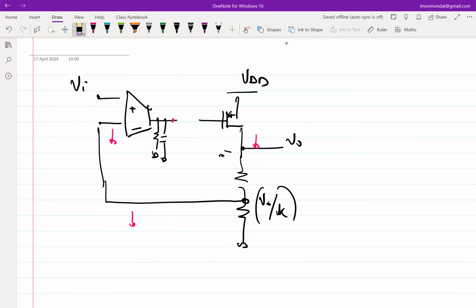So the thing that sometimes students get tripped over is the fact that just because we have made this a negative sign does not imply the loop is negative feedback if you connect everything to that negative sign. It will be negative feedback if and only if you go around the loop and you see that there is inversion happening, right? So that negative sign in this is only pertaining to the condition that if this voltage increases, what is going to happen to this voltage? So that sign is only limited to the block, not the loop, right? So loop can have its own settings.